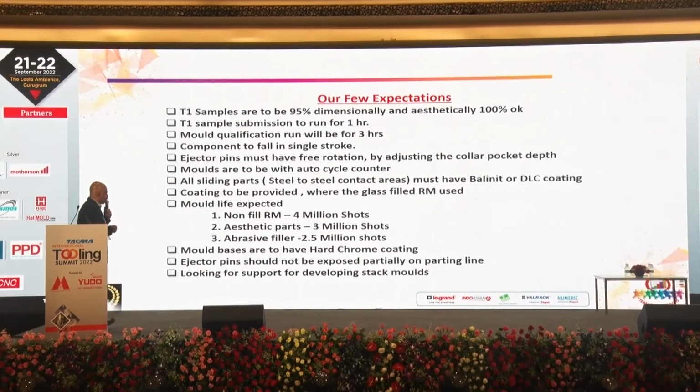For mold bases that have hardened chrome plating, the ejector pin should not be partially exposed on the parting line, because sometimes we do half parting, which damages the other cavity side.